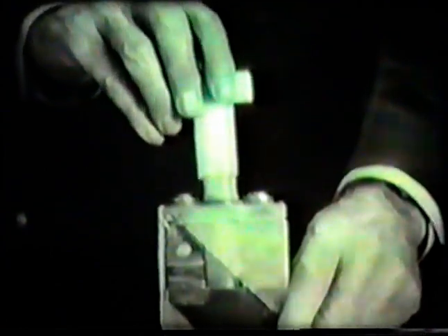Cell connectors replace the terminal posts of lead-acid batteries. Since the connectors are threaded, the individual cells can easily be disconnected and removed from a battery. On nickel-cadmium batteries, vent plugs are used rather than non-spill caps. These plugs are set to relieve gas pressure in the cell if the pressure exceeds 5 pounds. They also prevent electrolyte from spilling. Since the vent plugs are firmly torqued, a special nylon plug wrench is required to remove and replace the plugs.